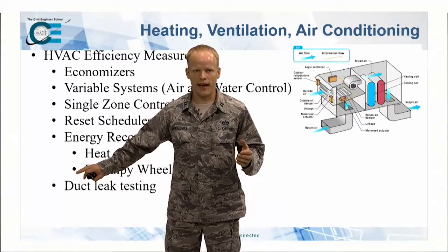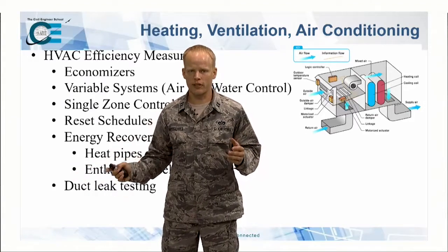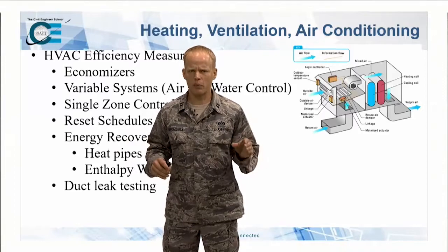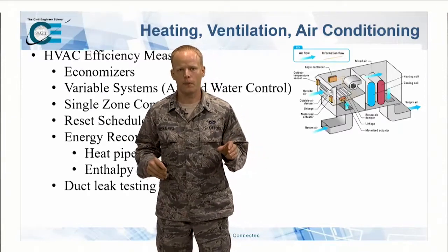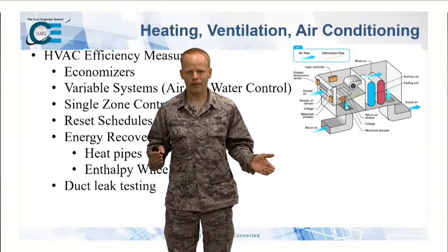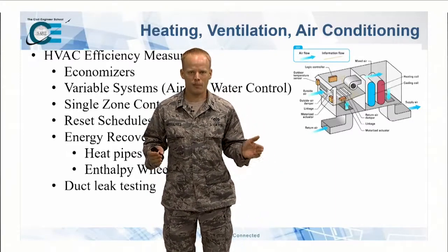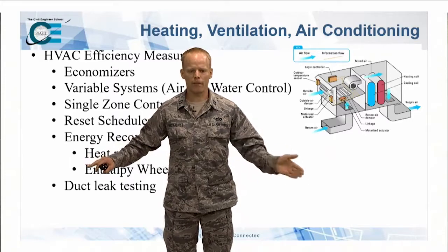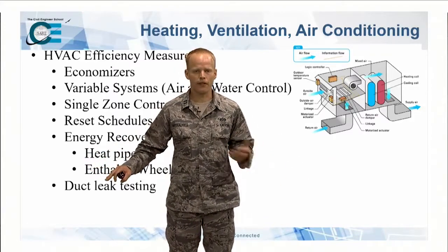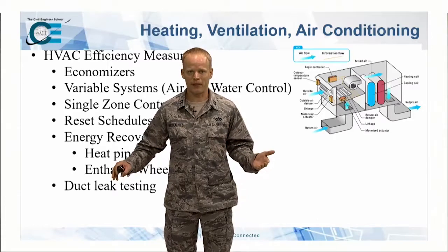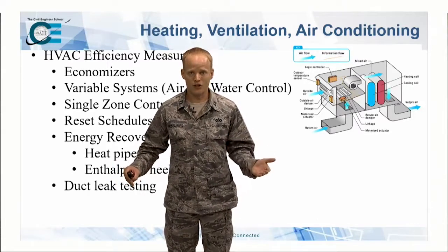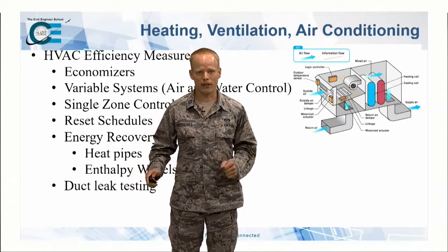It's hotter than the outdoor air. So a typical system, we would return that air and then recool it again and bring in as minimal outside air as possible, which is smart during parts of the day. But if it's, say, in the morning, we can save that energy by just exhausting it and bringing in possibly 60-degree air. We may not have to even cool it. And this is one of the things I did in my thesis, how is this economizer going to work? And yes, you save energy just by using an economizer.